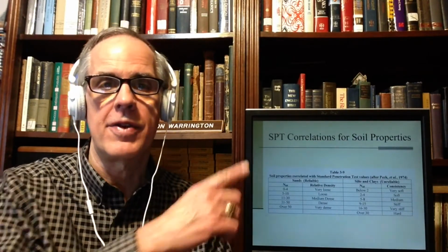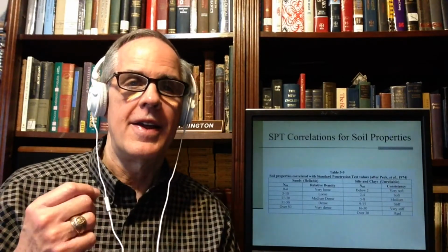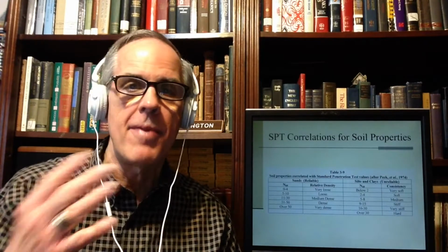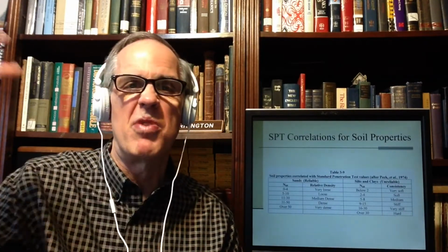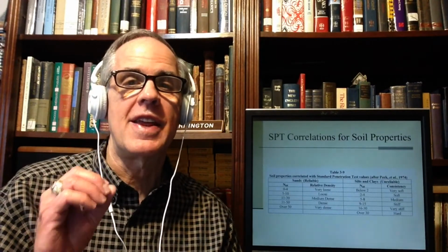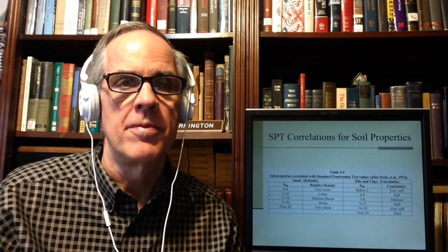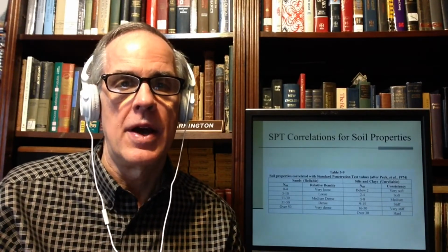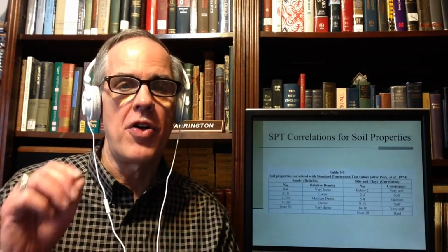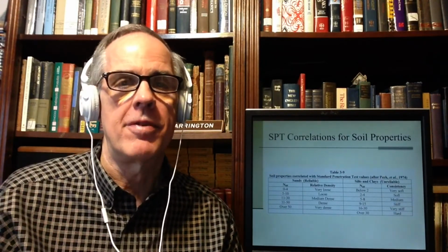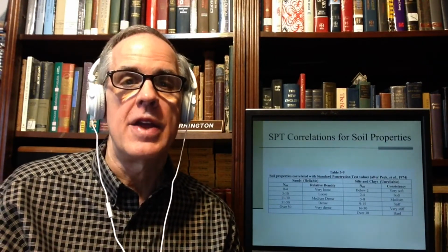And then you've got everything in between over here. When we say a clay is medium or stiff, or a sand is medium dense or dense, we're not just trying to blow smoke in your face. We're actually thinking about a certain type of sand with certain values, and we're going to get into more detail about how those designations can be used for standard values, which are a very useful interpretation of soil.